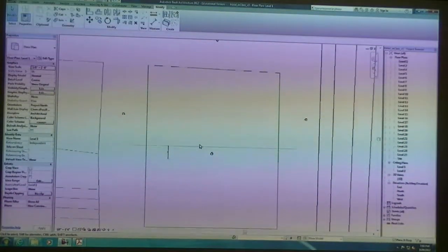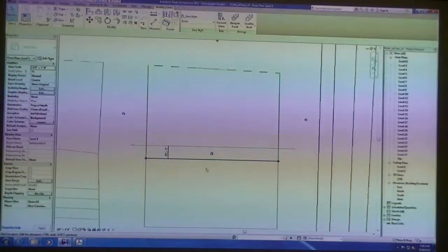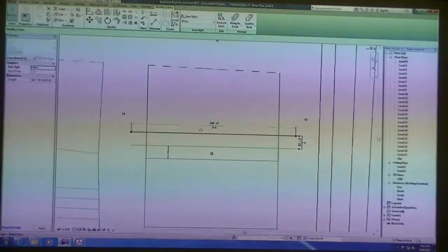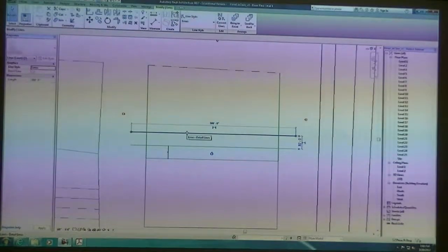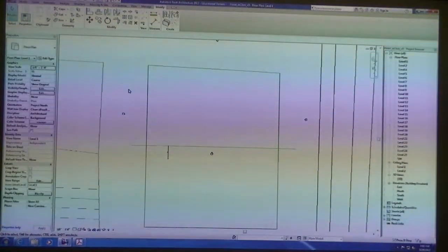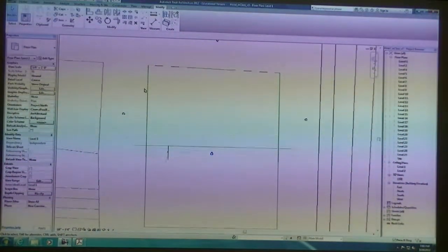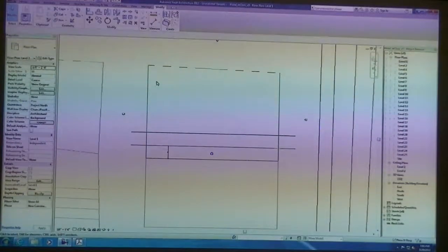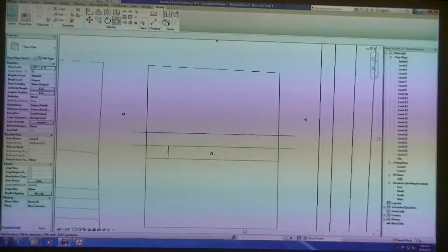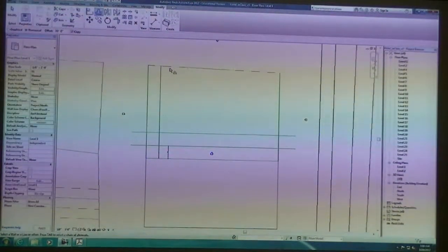So these are just multiple ways of finding 60 feet away from this building face is exactly where our building can kind of stop. I'm also going to say that our building setbacks from all 3 sides of the streets will also be 30 feet back. I'm just going to say we're just going to use 30 feet all around.